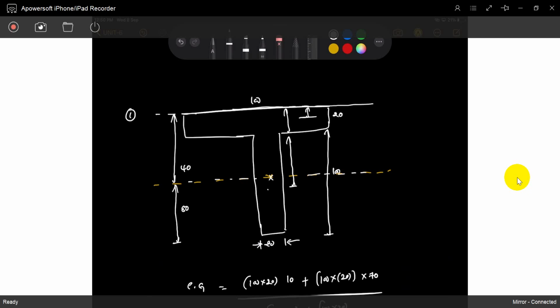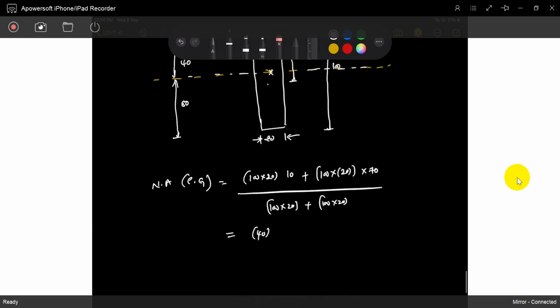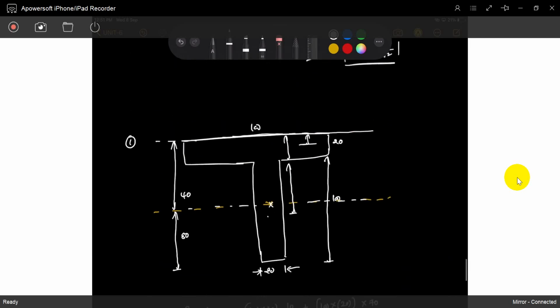That is the CG axis. Did you understand? Sir, what does the CG axis mean? Neutral axis for elastic analysis. For plastic, the neutral axis is the plastic neutral axis, or equal area axis. Exactly the line that divides both areas, divides the area into half. Where is it? You can easily say here, this is 100, this is 20, this is 100, this is 20.